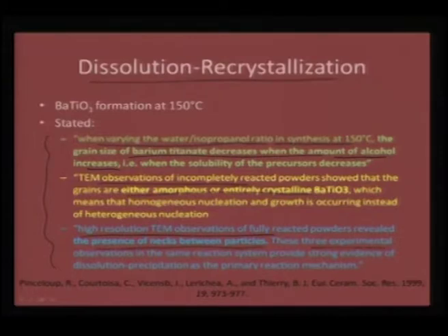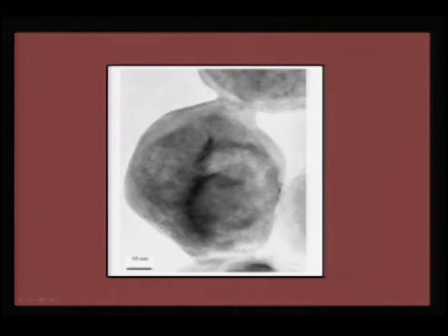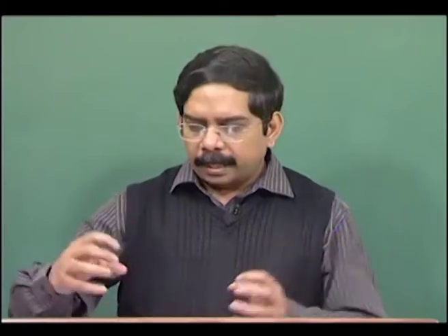These three experimental observations suggest there is strong evidence for a dissolution controlled recrystallization process which is occurring, and this necking can be seen here, and this is the necking area between two particles, which gives more indication that this is a dissolution induced recrystallization, otherwise these two will be separated.